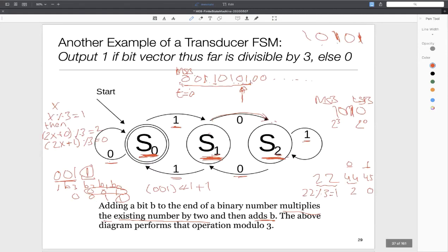This kind of stuff. The one thing missing out here is we don't know what bits represent the states, right? I know I have 3 states, and therefore I can say, hey, I need at least 2 bits, because I need to represent 3 states. But what should be the representation, right? Is S0 mapping to 0,0? Is S1 mapping to 0,1? Is S2 mapping to 1,0? Or do I have some other mapping?